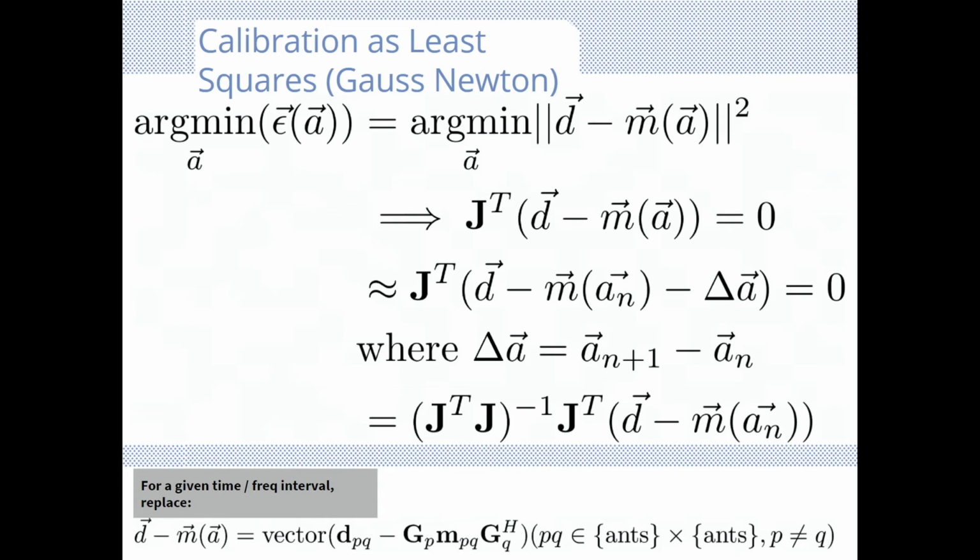Again, we can bin all the measurements into frequency and time variable bins, which depends on the signal to noise that we have, that we need to be able to solve. So a longer bin will give you higher signal to noise to solve for effects, but may negate highly temporally variable effects. So there's always a trade-off here, but we typically bin our solutions into these two-dimensional bins.